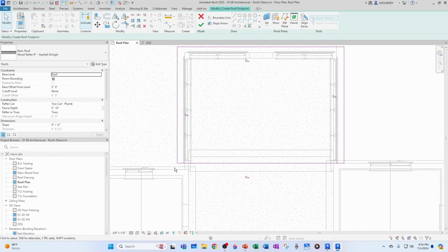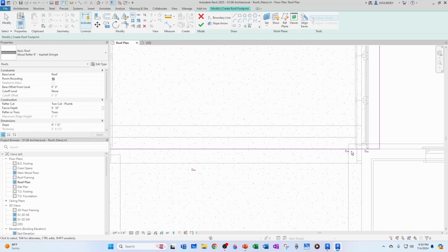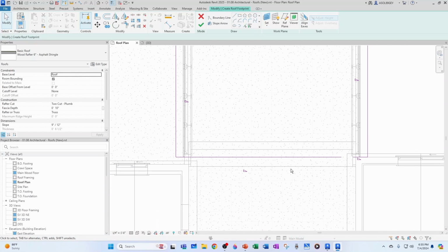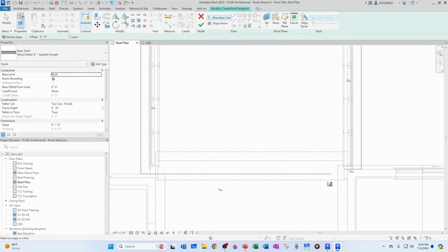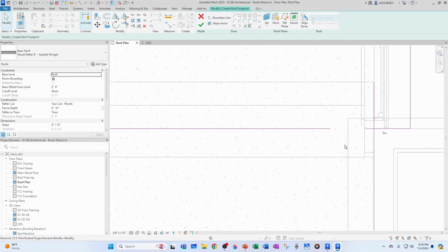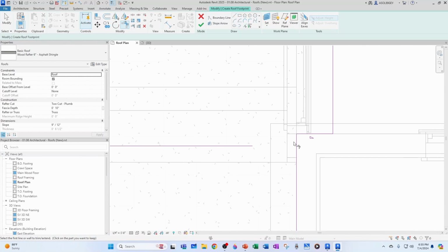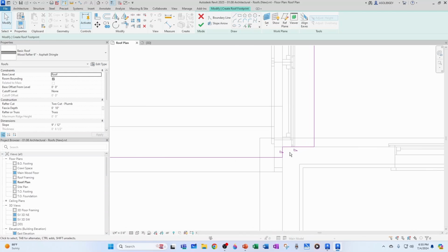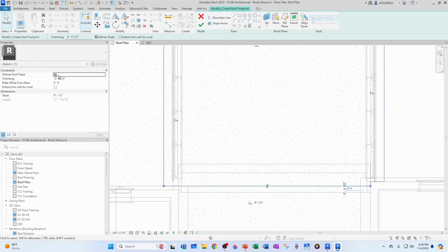There's actually a slight difference between this wall and this wall, so we're going to have to jog a little bit. So let's split here, delete, and we want to align to this face. And now we can pick lines. We pick this line here, we do TR to trim from here to here, and then we want to trim from here to here. Neither this nor this define slope, and then this one doesn't define slope either.